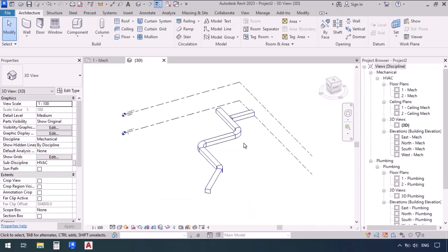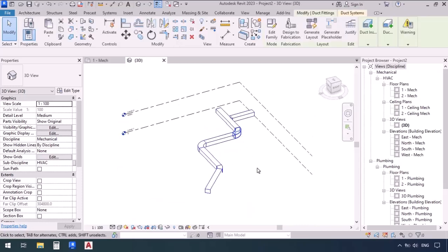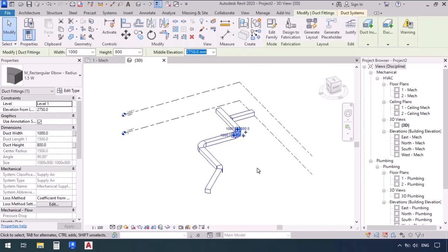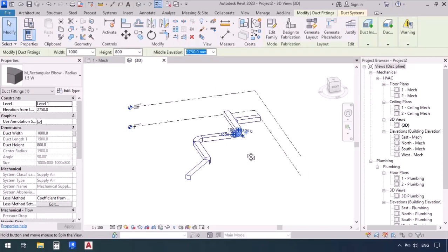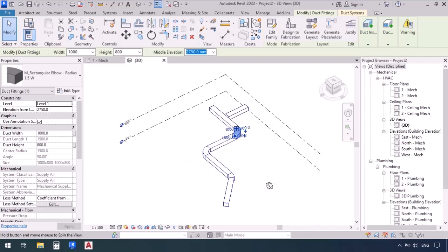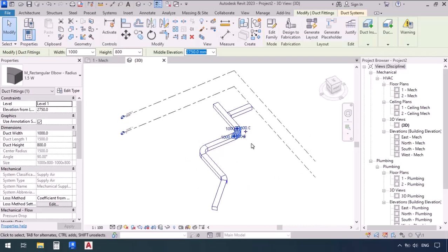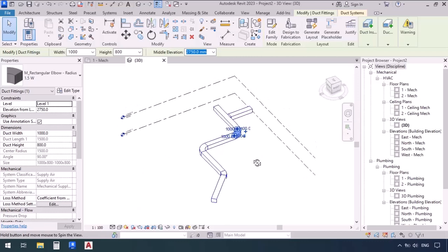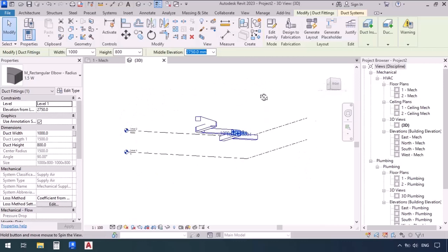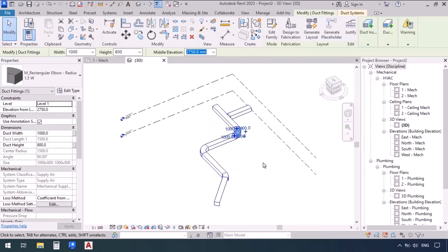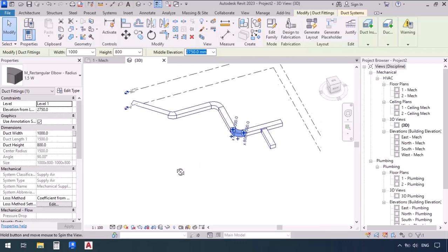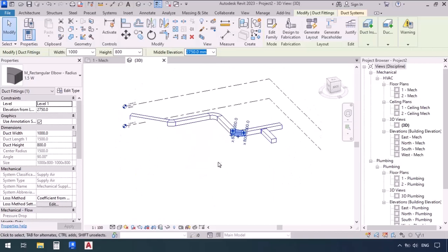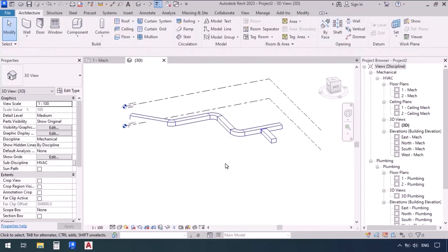And as I'm holding the Shift key and the scroll from the mouse at the same time, I can rotate everything. Now, if I click on an item so it would be selected, and then do that rotating thing by holding the Shift key and clicking the scroll, with this selected item as the center, everything will rotate. As in, the center of my rotation would be this item right here, and all the other items will revolve around it. So I can rotate by the Shift key and the scroll key and see my model from different angles.